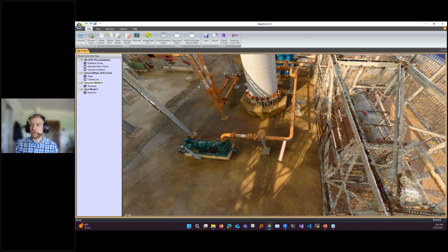If you're trying to extract 2-inch conduit or 1-inch conduit, that's not going to work, right? But if you want to do walls, large I-beams, or piping that's 6 or 8 inches, that can actually work pretty well, if it's not too far away. If you're trying to model stuff in the ceiling that's 30 feet in the air, that's going to be a problem. It's really susceptible to distance.